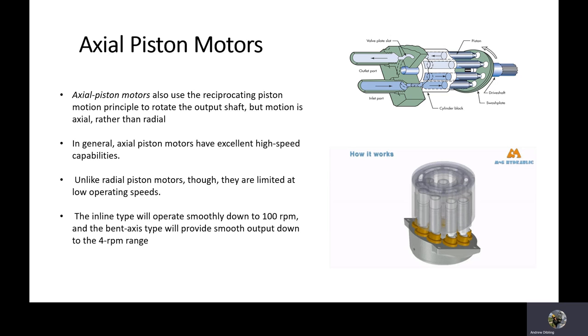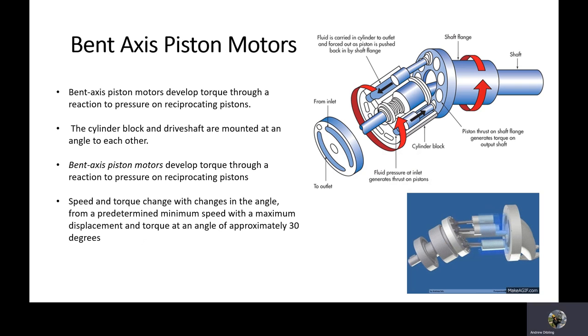If I'm moving, for instance, steel rollers with moving tons of hot steel, and I need to move it slowly to move it into the cutters or to part of the processing, I might want to use an axial piston motor because of the fact that I can control the speed very closely by changing the angle of that swash plate, and therefore changing the torque and the speed of the output of the motor.